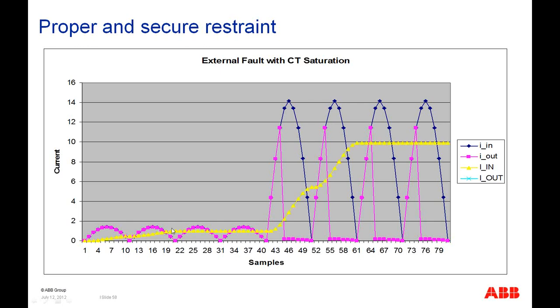So again, we have our RMS current for the input, which is still steadily increasing, and our RMS current for the output is going along the same lines as the input, even while a fault occurs. You can see these two are both together while the fault is occurring, then at a certain point the output drops down to a minimum value while the input curve keeps going up. The relay sees the two currents are the same, and they both start rising like there's an internal fault.